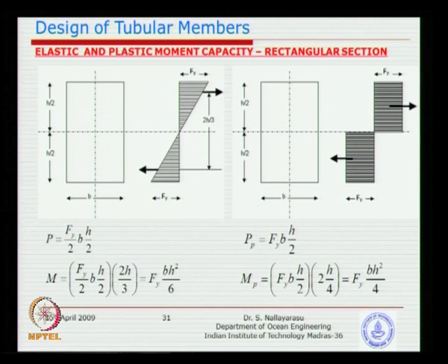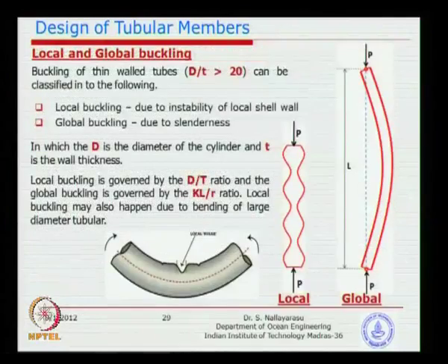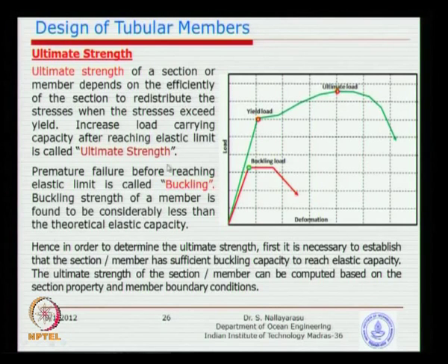So if you look at a rectangular section, I think most of you must be familiar with this. We are just looking at how the cross section of a beam column affects the ultimate strength. How do we compare? It is very simple. Evaluate the elastic strength within this area. Basically the green line is the elastic strength, and beyond the green line, after the yield point, is called elastoplastic, or probably the ultimate collapse capacity.